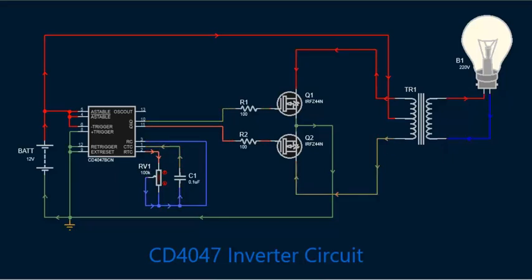First, what is an RC Snubber Circuit? An RC Snubber Circuit is a simple but critical protection network used to suppress high voltage spikes and ringing caused by the switching of inductive loads. It consists of a resistor and a capacitor, a C, connected in series, typically placed in parallel with a switching component like a MOSFET, or across the inductive load itself.